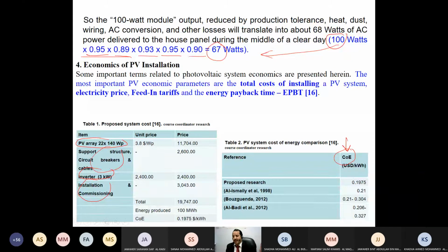As an example, if each kilowatt hour costs me 10 paise, compared with the electricity coming from the grid, which may cost me 25 paise, definitely I go for solar because it's cheaper. So from this calculation, I want to know, is it cheap or is it costly? If it is cheap, I will go for this option. Many elements could help. As an example, if we have a feed-in tariff, or let me say incentive support for renewable energy in the country, then this will help.